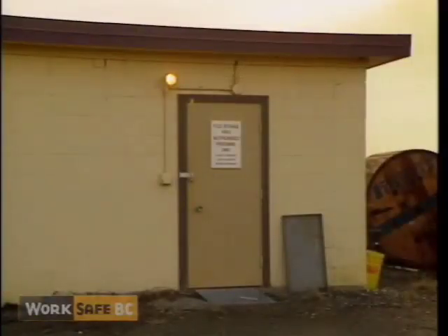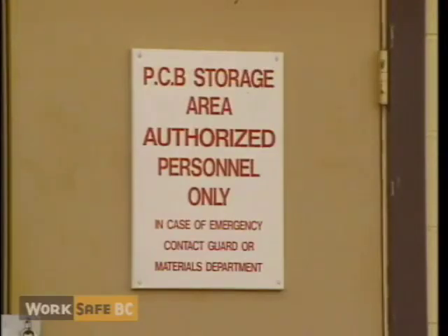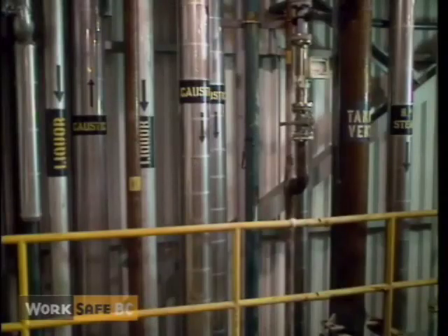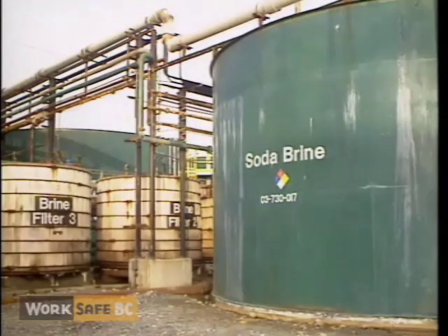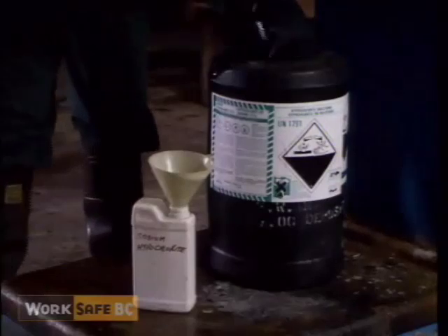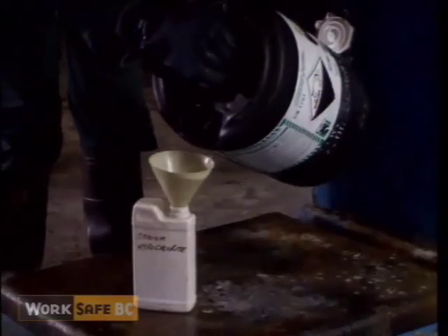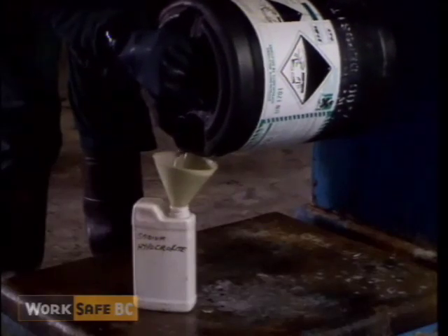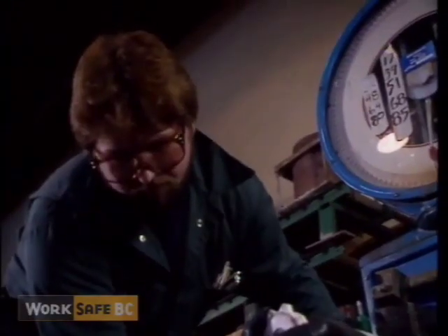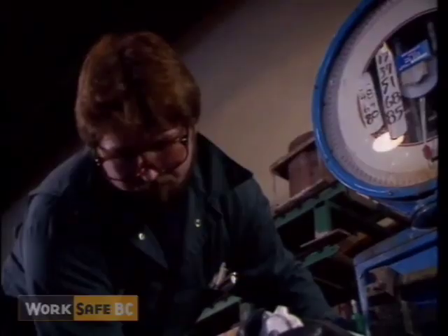Other means of identification may be used to identify locations where hazardous waste produced in the workplace is stored, to identify controlled product transfer systems, such as pipes or conveyor belts, the contents of reaction or process vessels, or to identify the contents of portable containers that are filled directly from a labeled container and will be under the control of the worker who transferred the product to the new container for use on the same shift.